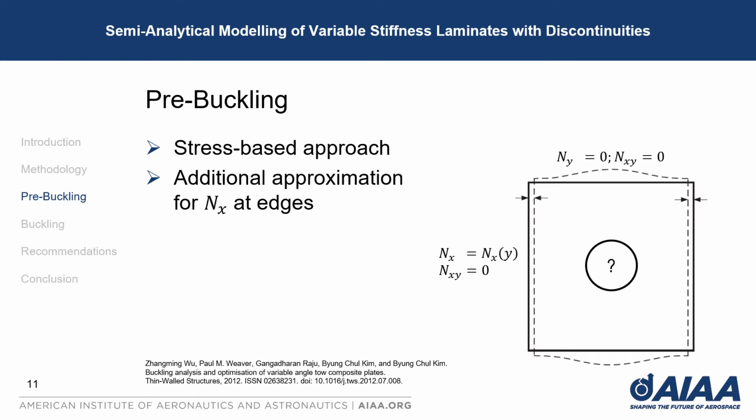Along the cutout edge, no suitable shape functions were found to comply with the boundary conditions. Rather, a residual thickness approach has been taken, where the model takes the laminate to be continuous, but the thickness of the cutout region is reduced by so much that it deems it cannot carry any load. So the load must be distributed around this cutout region.